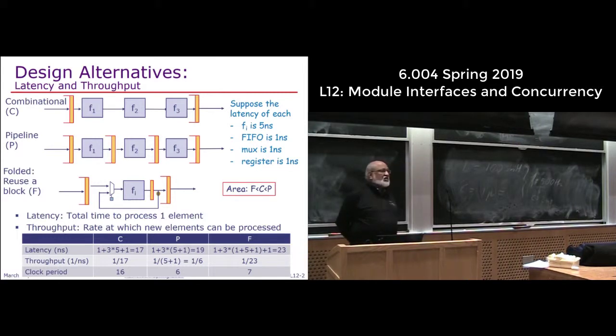That's what you saw in multiply by repeated addition, where we could get away with having just one 32-bit adder circuit, because we just kept the results in a register and used it over and over again. So it's smaller than if you had a combinational multiply circuit.